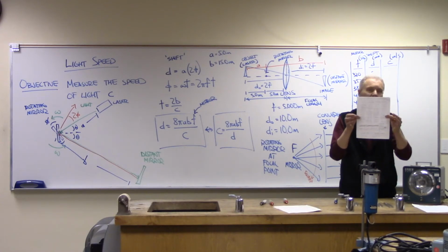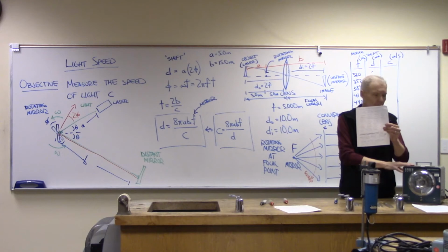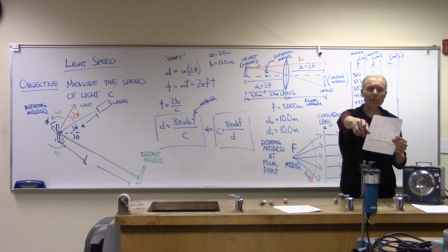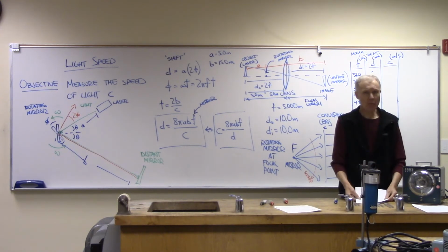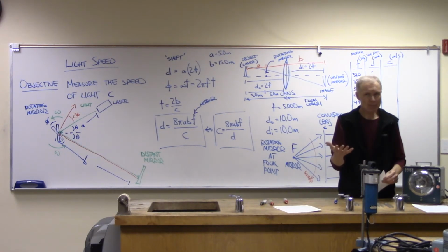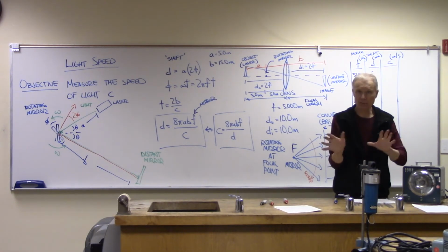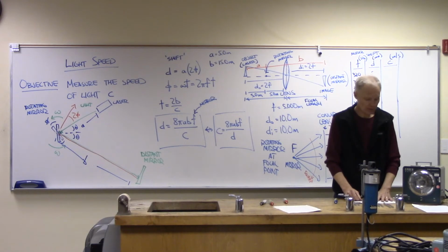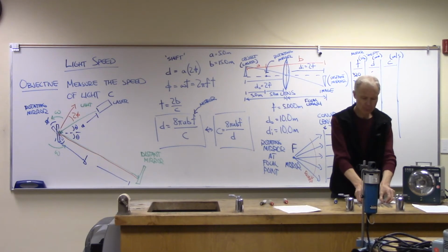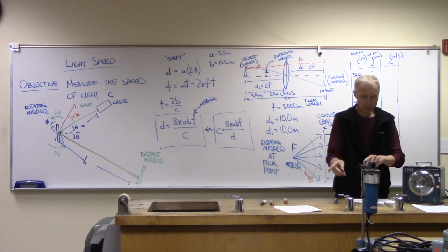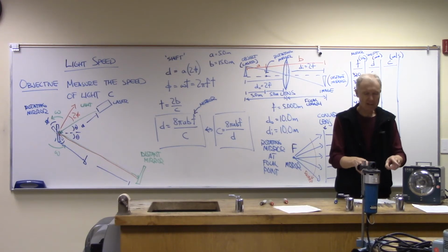So I did a calibration of the strobe light based on these tuning forks, and then applied that to the motor. So at that point, I was feeling pretty good. Everything seemed to be pretty consistent. I cross-checked all the frequencies because these frequencies are in a ratio of 4 to 5 to 6 to 8. You guys may have seen that in Physics 4A, looking at harmonics.